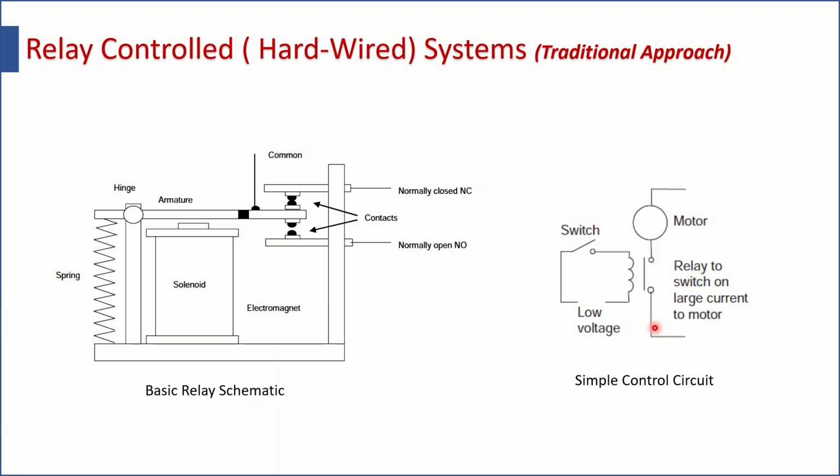There can be a microcontroller or a PLC or a processor. Normally such devices are a bit delicate and they are not able to conduct very heavy current. They cannot operate under very heavy voltage. So under such circumstances you need to isolate the logic part of the circuit and the power part of the circuit. If you have a three-phase motor working at 440 volt and drawing some 9 or 10 amperes of current, and you want your logic controller to directly connect to the motor and turn it on, it is not going to be possible. Even your controller can get damaged out of that effort.